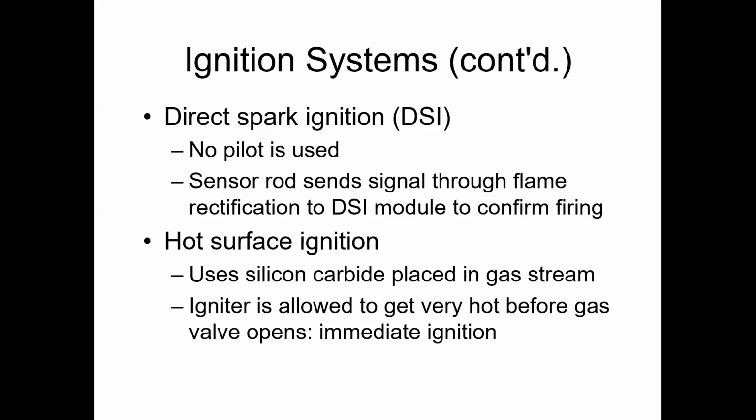You're looking for about 40 to 90 ohms typically, but anything below or above that is definitely abnormal. But always check your manufacturer if they've got a different style or anything like that. It might be different readings you're looking for.